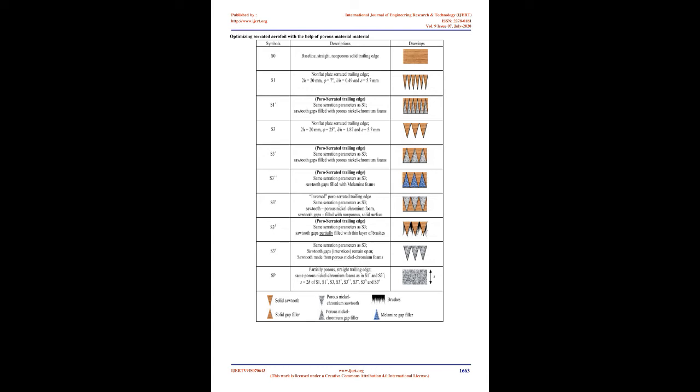Due to interference between acoustic radiation produced at the root and the tip of the serrations. St_d below 0.13, region of noise attenuation, R1. 0.13 to 0.7 St_d, region of noise increase, R2. 0.7 to 1.4 St_d, region of attenuation in the blunt trailing edge vortex shedding noise component, R3.